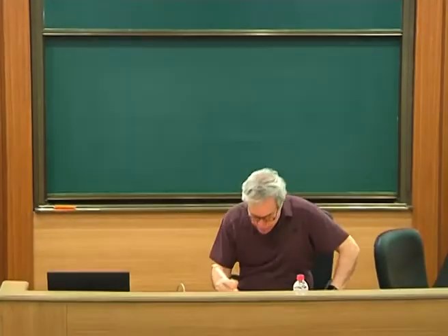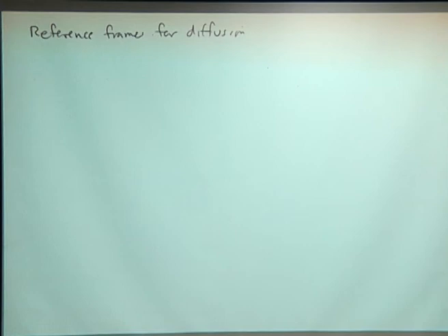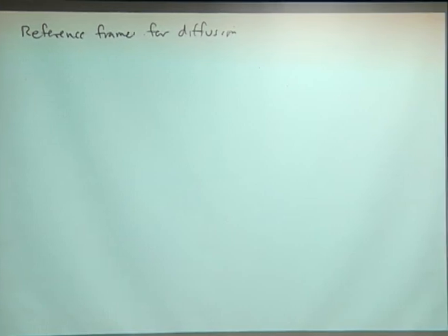And that really gets into the whole issue of reference frames for diffusion and the frame in which these diffusion fluxes are written. That turns out to be very important, because otherwise there's no way of connecting what you've learned in your undergrad class with things like phase field models that have this relationship but start off in this kind of representation of diffusion fluxes. And the key here is the reference frames for diffusion. And so imagine